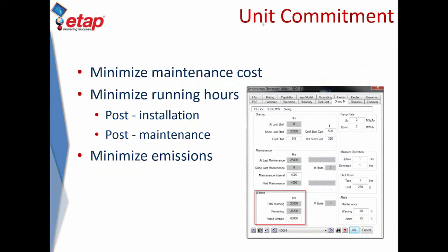And then when we deal with unit commitment for microgrids, we're actually dealing with starting and stopping generators based on these objectives. The unit commitment in a traditional sense in a utility is quite different, because that actually relies on day ahead forecast. This unit commitment actually relies on a much shorter term, a shorter horizon forecast. So we are able to actually run this on a few second to few minute basis, because in case of renewable energy, the wind and solar output can dramatically change in a matter of seconds to minutes, depending on the situation.